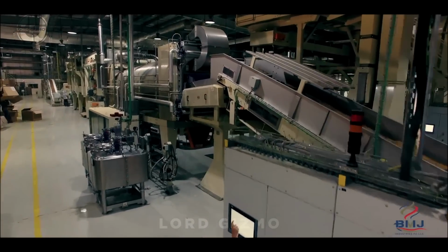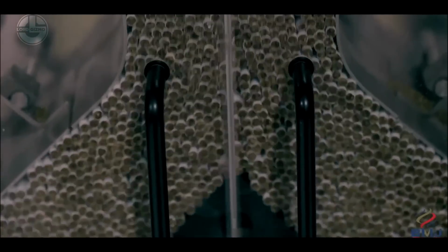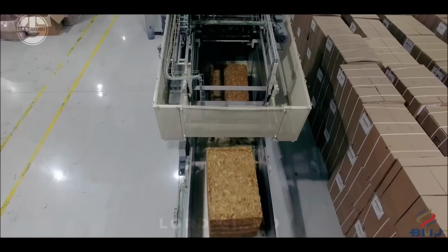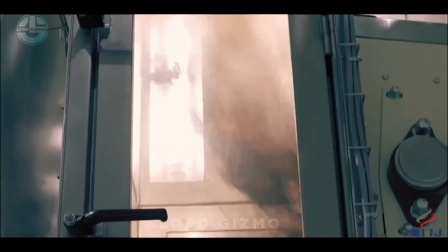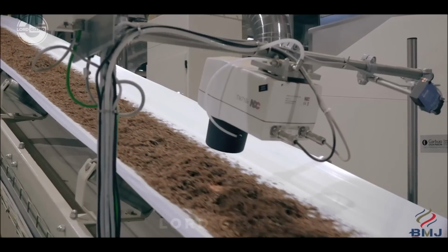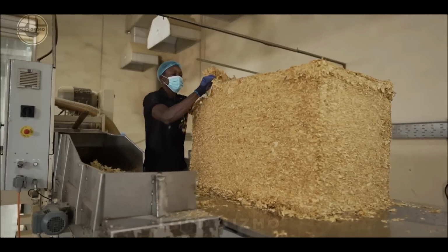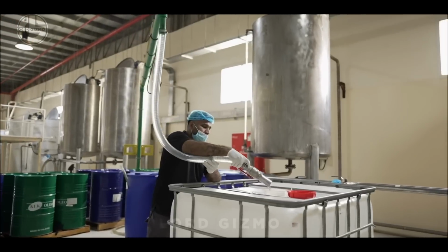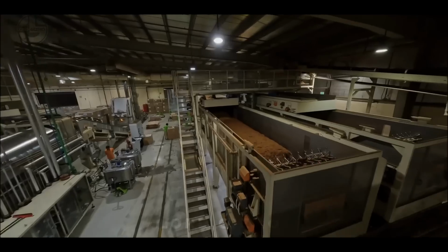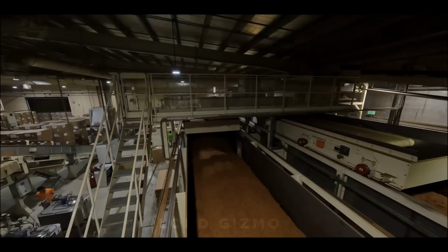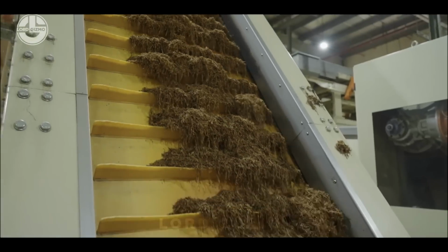In manufacturing facilities, a chain of various machines continuously produces thousands of cigarettes every minute. Firstly, the ready tobacco, in the form of pellets, is passed through the threshing line. This process breaks apart the ready tobacco to lose its rigid bonding, so tobacco can be filled into the cigarette rods. But before filling the cigarette, the threshed tobacco is blended with some flavoring. After that, the tobacco is blended thoroughly to ensure uniform distribution. This process may also include the addition of humectants to maintain moisture levels and enhance the smoking experience.